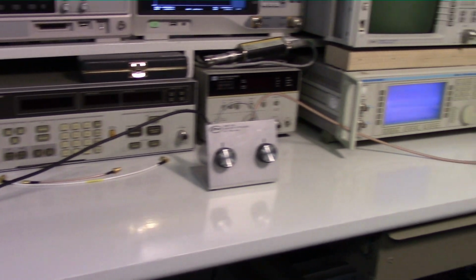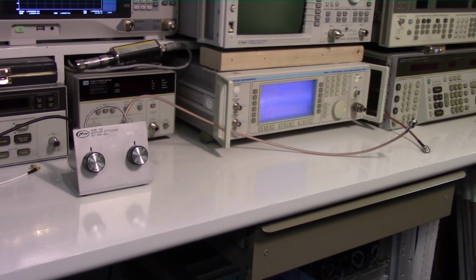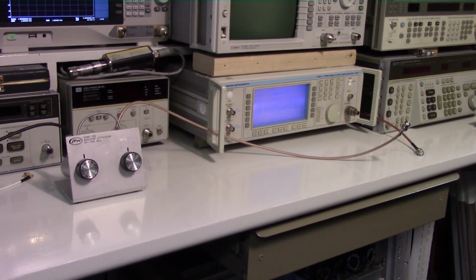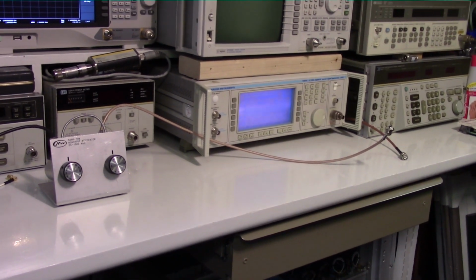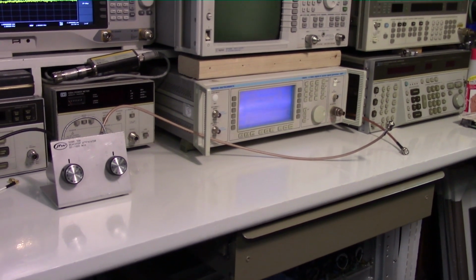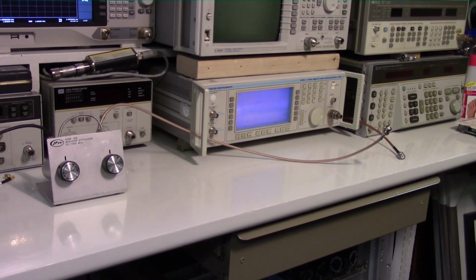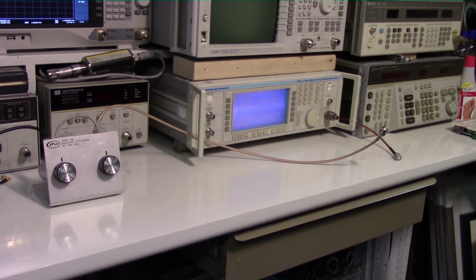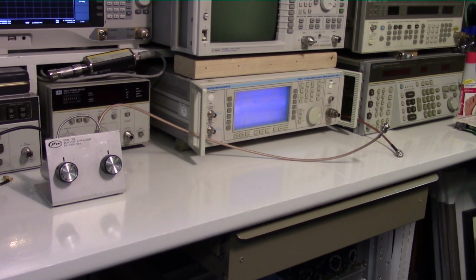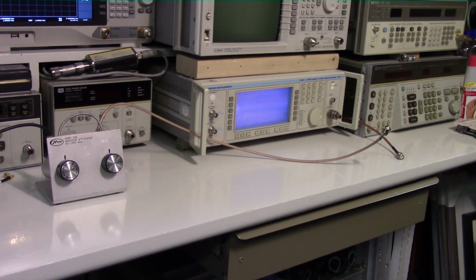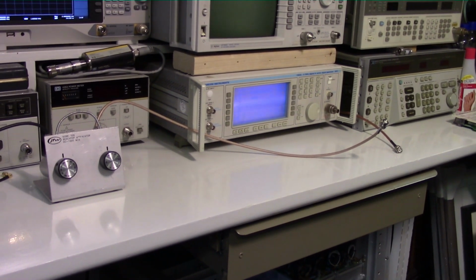But it's always a good idea when you're working with very, very weak RF signals like this. Remember I said make sure that you use a very high quality double shielded cable like RG142 or RG223. You want to do that because